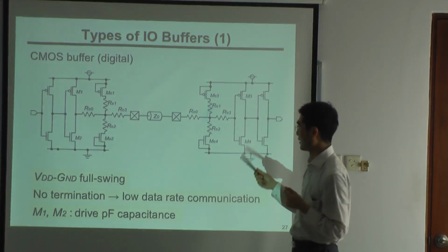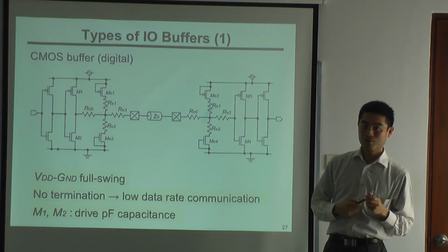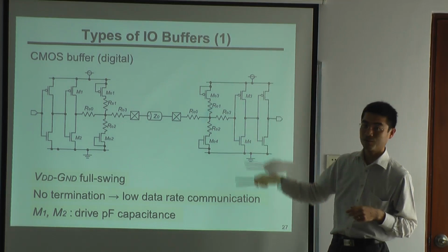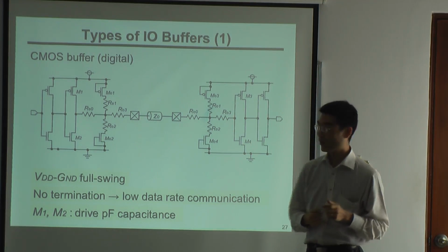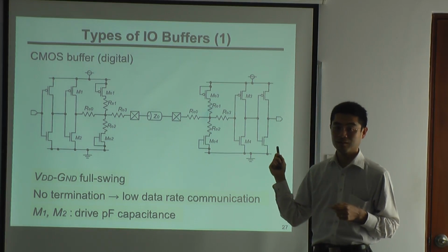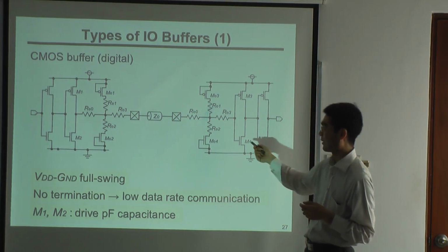And for input buffers, these types of input buffers have to have ESD protection because they are directly connected to the gate, and that is weak against ESD.